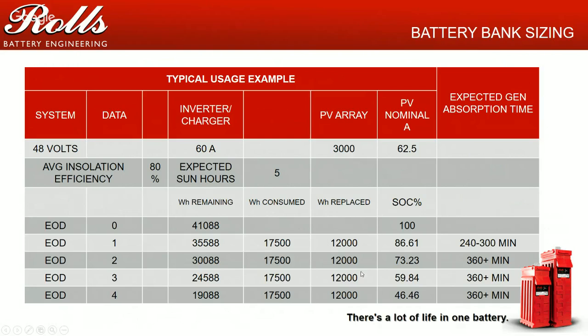No matter what the weather is, even assuming you're getting full production from your sun, your PV array is not able to keep up with the batteries. Unfortunately, I see a lot of possible warranty submissions that are systems designed just like this.